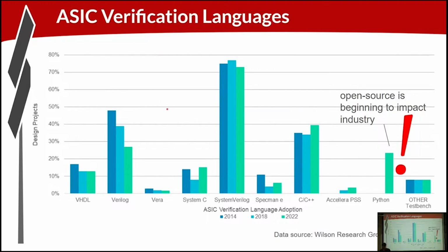A look at verification languages. So you can use VHDL or Verilog for your verification environment. I don't know why Verilog is so much bigger than, System Verilog is bigger. The delta of System Verilog from Verilog is mostly around verification functionality. UVM, you may have heard of, is a library built on the System Verilog features for doing verification. Vera is a language that, you can see, didn't get huge traction for doing verification. Some of my former colleagues were off in that world a bit.